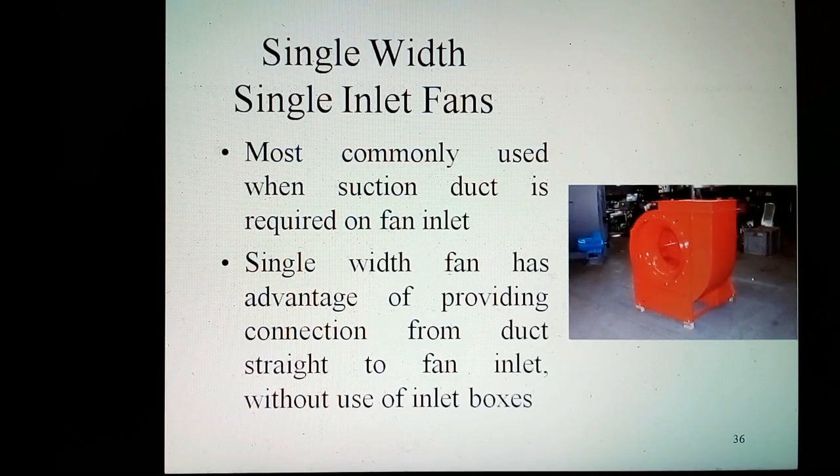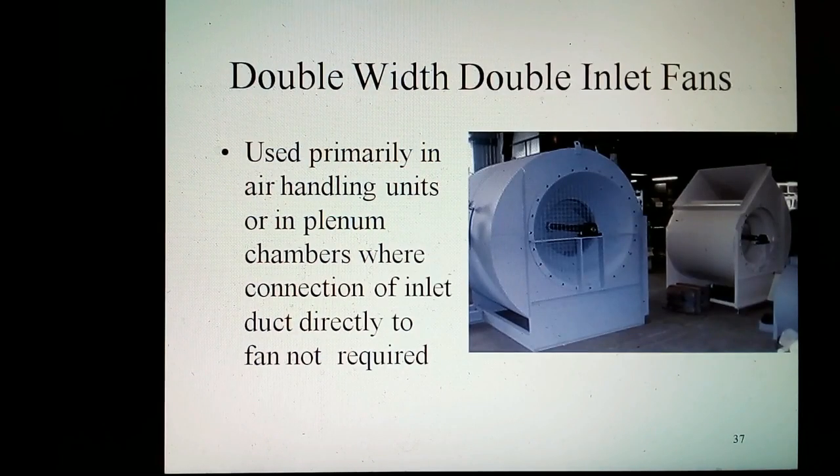Single-width, single-inlet SWSI fans are most commonly used when a suction duct is required from a fan inlet. The single-width fan has the advantage of providing a connection from the duct straight to the fan inlet, without the use of inlet boxes. Double-width, double-inlet DWDI fans are used primarily in air handling units or in cleaning chambers where the connection of the inlet duct directly to the fan is not a requirement.